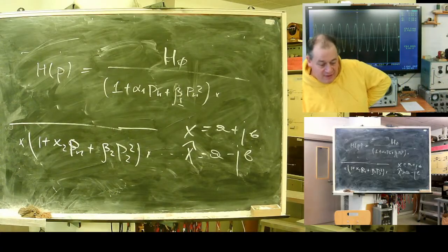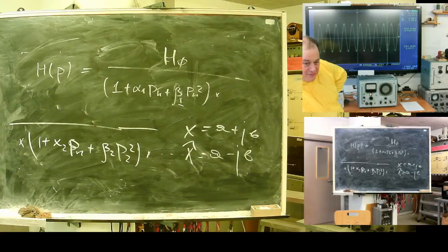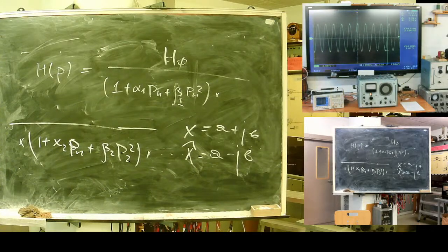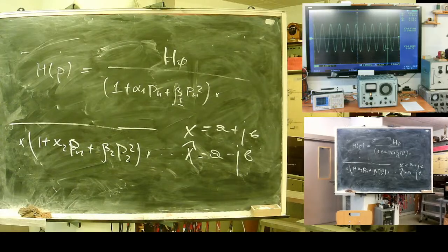If you have 12 or 15 channels, you will have a set of active filters. Some devices are designed in an interesting way. It has first passive filters and a transformer input, and then multiplexing, where this point is a multiplexer switch. And the active part, an op-amp, is one for all channels, switchable.